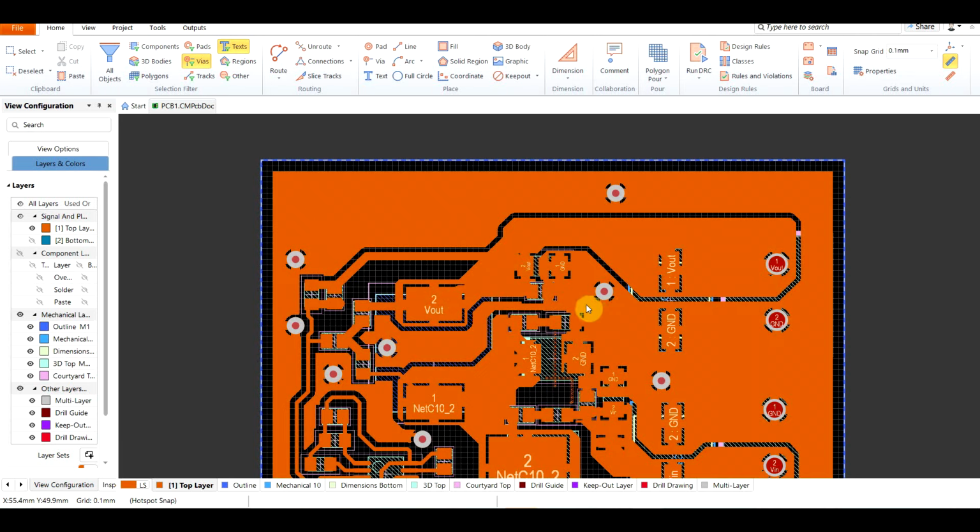But as we saw with our experiments, where a similar principle is applied, this will not guarantee a precise voltage at the load if it's far away from the supply. Next best thing is remote sensing. Rather than regulating the voltage at the output of the power supply, you can look at the voltage that reaches the load and regulate that. Now, this will not always be a possibility based on how the power supply is built, and you can only regulate one point, so it won't really work with multiple loads connected to the same net.